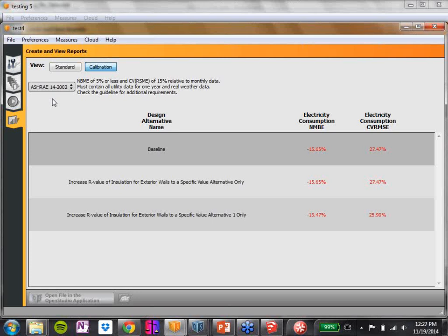I'm still new at this, so still learning, but I would say set points and schedules have been the main issues. Lights that are supposed to go off on the weekend that don't, set points in the building that change, unoccupied offices that are supposed to be off but are still on. Getting a handle on those is really important.